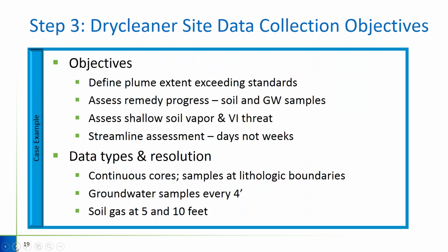So, condensing all of that into specific objectives: defining the plume extent exceeding standards, assessing the remedy progress with soil and groundwater samples, assessing the vapor intrusion threat, and doing all this quickly. They didn't want to be out in the field for weeks and weeks at a time. So in terms of the resolution, the soil samples were going to be done with continuous cores, and then rather than predetermining what interval was going to be sampled at,